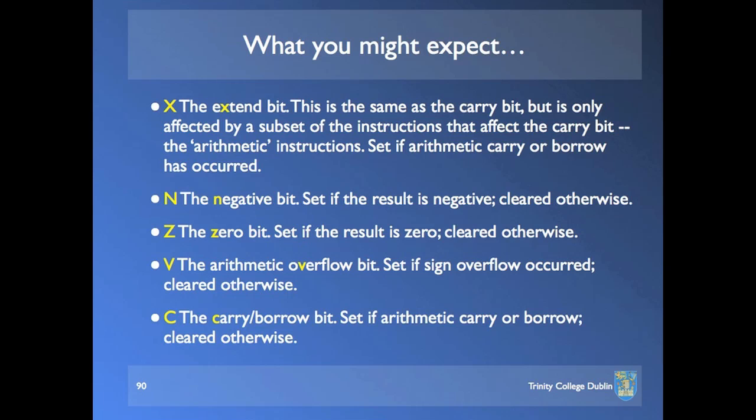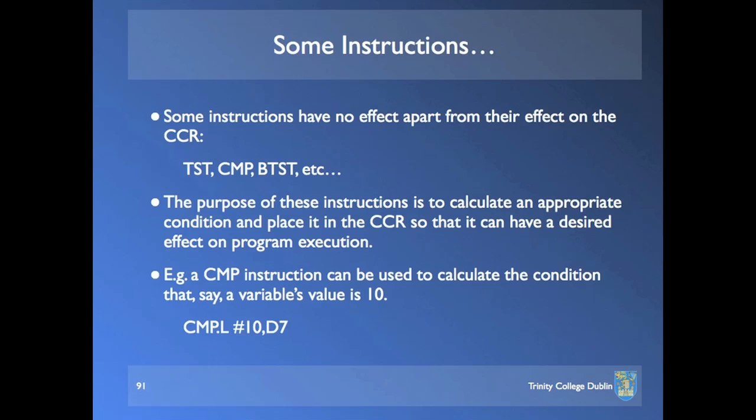The piece of code that I'm thinking of was this. We had move a byte from A0 into, was it D1? I think it was D1, okay? And then we had compare the byte with 0. Okay, and then branch if the Z bit was set to finish. I think that was what we had written down.